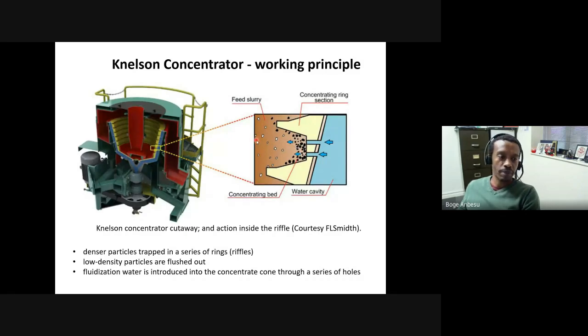In other words, light particles cannot withstand the flow of water against them, and therefore they remain suspended, while dense particles will be trapped here. After some time, you would have an accumulation of dense here and light in here. Because you're constantly feeding, whatever is in the chamber should be rejected and collected as an overflow or as a discharge.